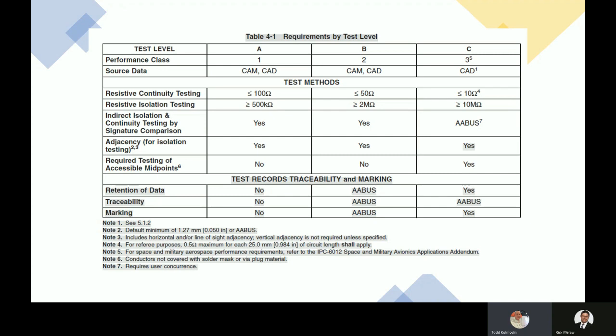And when you see a statement like that, where it says the maximum rated voltage of this PCB is 12 volts, you must remember that that is a statement. That is not telling you what to test the board at. They're telling you that in the duty cycle of this board, the maximum rated voltage that it will see will be like 12 volts. Now, you want to look for something where they're telling you to test. If they say test voltage shall be 12 volts, okay, then you're wrapped into that and you have to test at 12 volts.